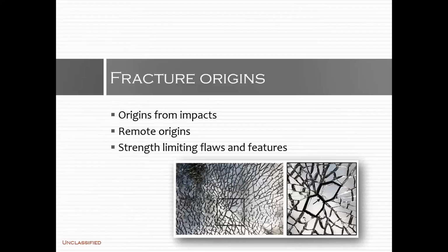Tempered glasses are manufactured to break into many small fragments when fractured. The two glass fragments adjacent to the fracture origin are typically polyhedrons with a greater number of sides than the other fragments and are also typically larger. This can make it easy for examiners to visually identify where the fracture started, even if the fragments are no longer together.